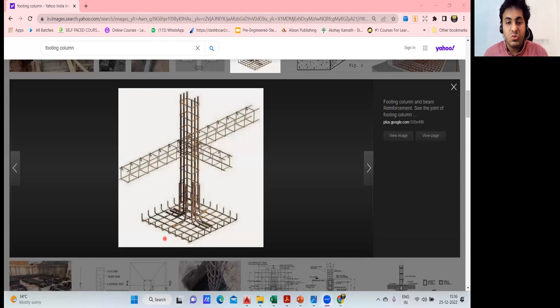Yeah, you understood now what I did. See, this is actually a footing for me. Let us say my footing height is up to here. From here is my ground level. From here, my excavation is going to start. This was actually 2.5 meters, if you remember the drawing. So 2.5 minus, you'll see these lateral ties we have. It is not going to start exactly from the bottom. It will start from here. This is the first lateral tie we are going to find.